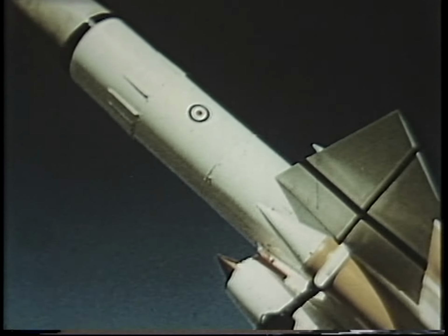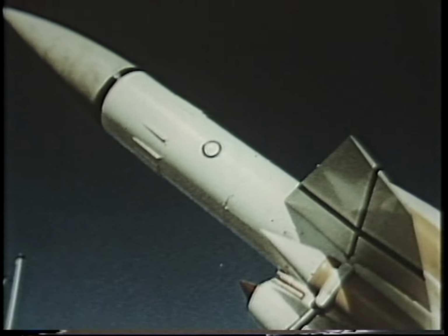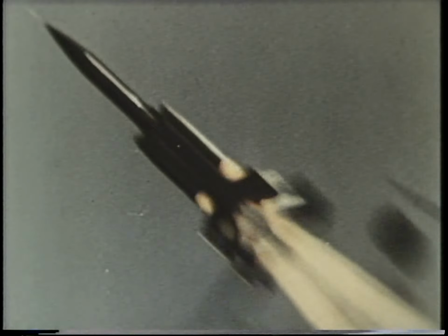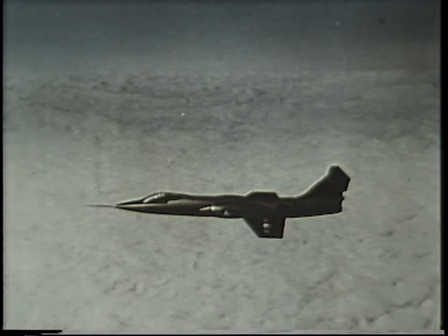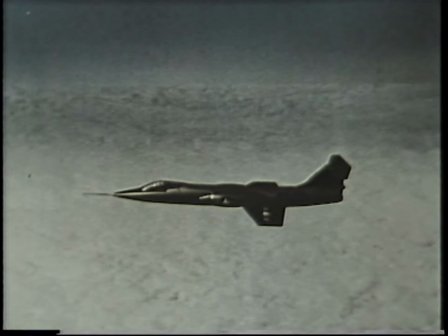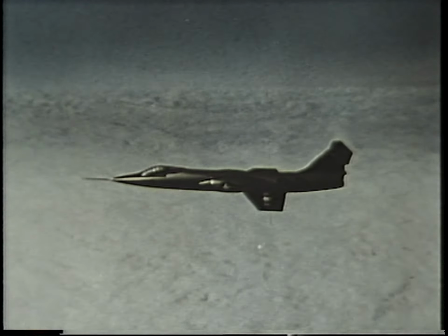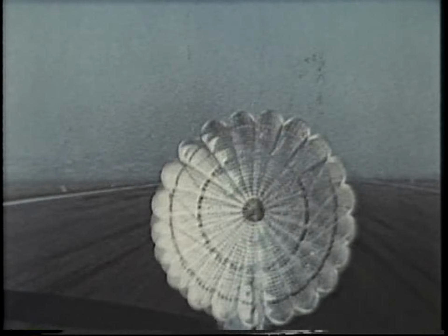The trouble about these wing sections is that they give very poor lift at low speeds. They can be used on missiles such as this one with double wedge wings. But for manned aircraft, which have to take off and land, it's not so simple. Very long runways are needed, and sometimes even extra braking devices.